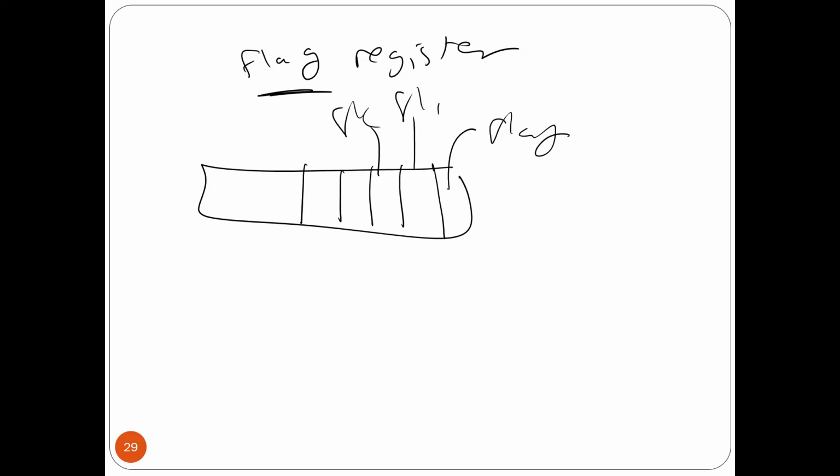So what do you mean by flag? Yeah, something like a flag. Why? Because if this is a 1, it means something. If it is a 0, it means something else. This is the meaning of it. Last time, I explained 2 flags, and I'm going to explain more today. One flag we call the zero flag. We have the negative flag. What you should understand, and that's what you're going to see tomorrow as well, is that these flags are hardware flags, physical devices. These flags are automatically updated after executing every instruction, automatically.